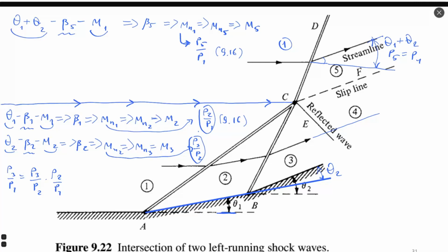That's it. So Mach number we know. The reflected wave, I think it's an isentropic wave. It's considered as an isentropic wave, not a shock wave. In such case, stagnation pressure remains constant. And according to isentropic flow equations or Appendix A, which represents these equations, we can calculate the change of Mach number.